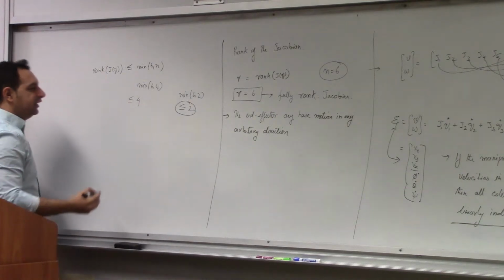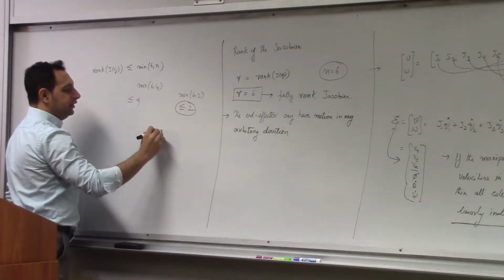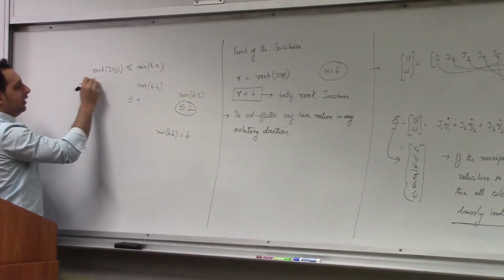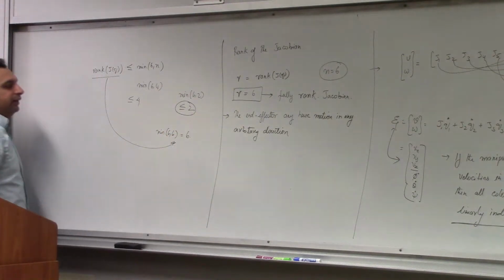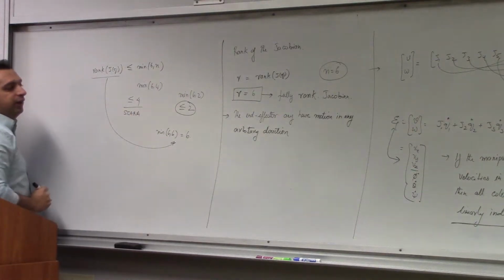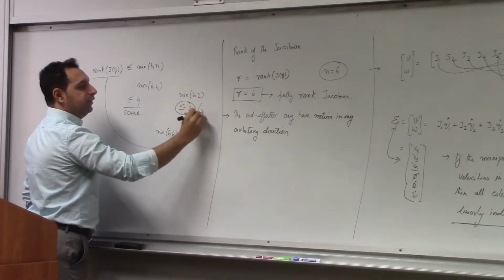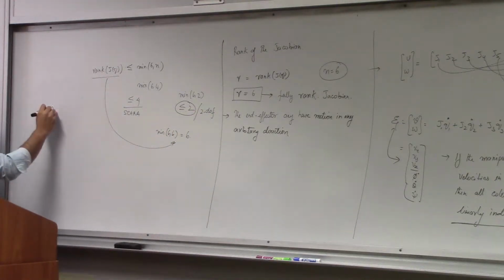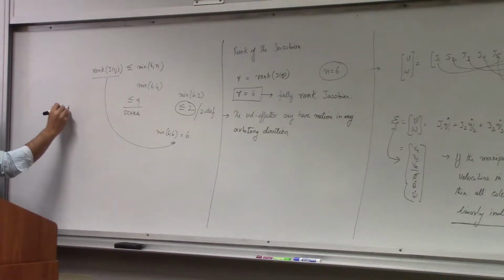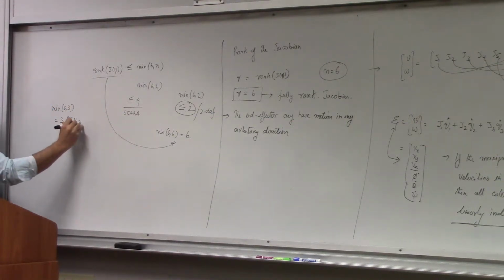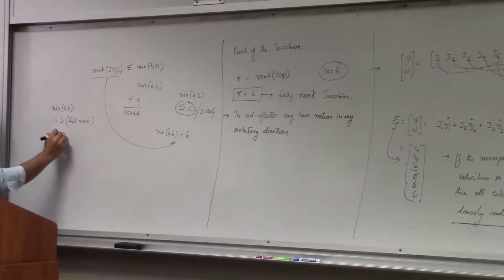If you take a 6 degree of freedom manipulator, the minimum of 6 and 6 is 6. So when the rank becomes 6, that means it's full rank. In the case of a SCARA, 4 is a full rank. In the case of a 2 degree of freedom manipulator, 2 is a full rank. If you have a 3 degree of freedom manipulator, 3 is full rank.